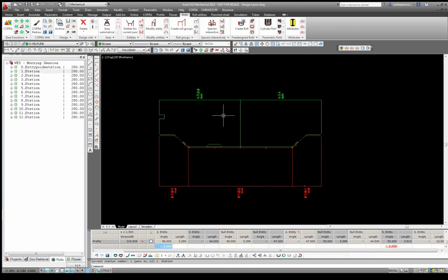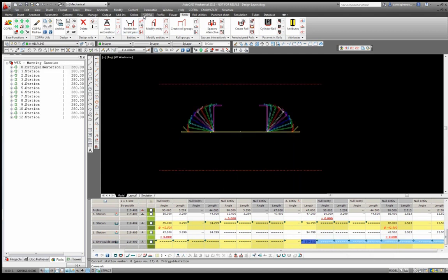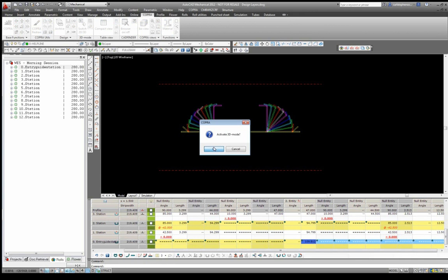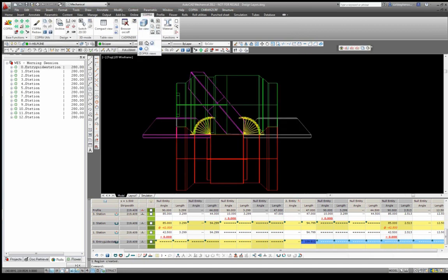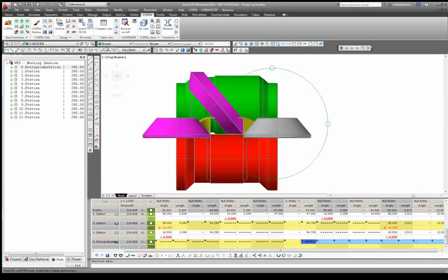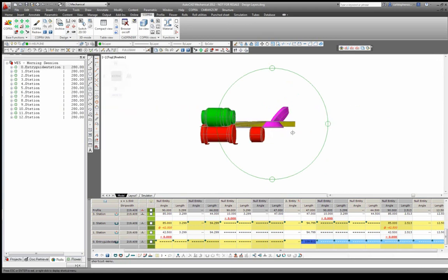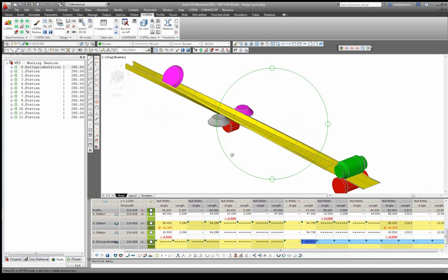So now we can look at some 3D possibilities. With Copra RF 2011, we can highlight in our spreadsheet here, and then we return to the Copra menu here, and switch to 2D, 3D, and activate the 3D mode. And within a few seconds the rolls are drawn. And of course, if we go to the Copra Views menu, we can hit Realistic and see them. And then with the axes we specified earlier, over here, you can then look for roll collisions between stations, etc. So you have a quick handy tool to see if there will be any conflict in your roll tool designs.